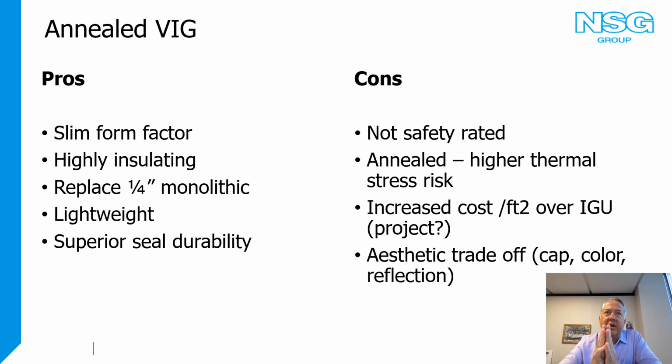The cons, when you think about an annealed VIG product: it isn't safety rated. There are some ways you can get around that with some lamination or safety films, but it's not a fully safety rated product. Because it's annealed, you're going to have some potential for higher thermal stress risk. So you definitely need to do an evaluation on all the different projects.